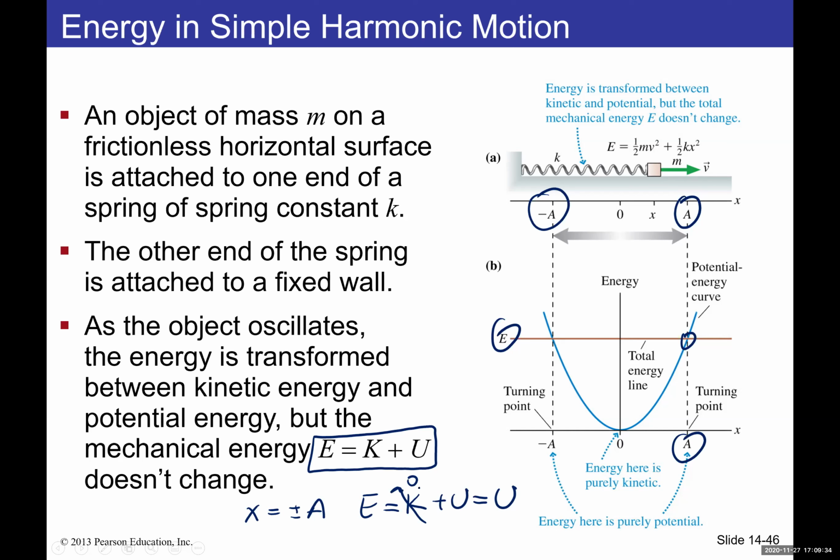And after that, as you let go, the spring force converts that potential energy into kinetic energy every time it reaches the equilibrium. So that's why you can say potential energy is zero at equilibrium, and all of that energy is now kinetic energy. Then kinetic energy converts back to potential energy when the spring system goes from x equals 0 to x equals negative a. That means the energy goes back and forth between kinetic and potential.